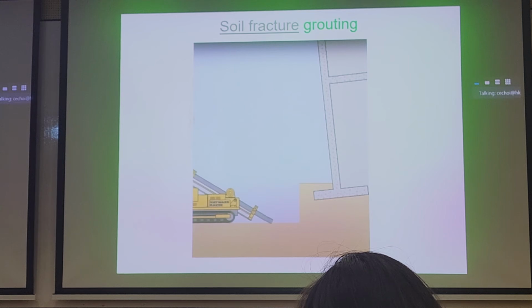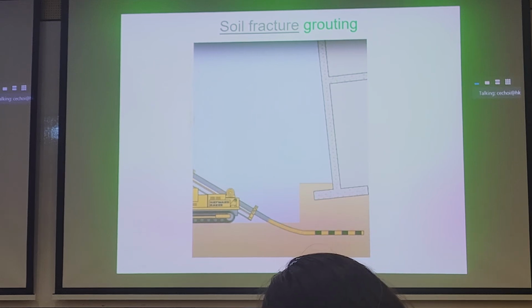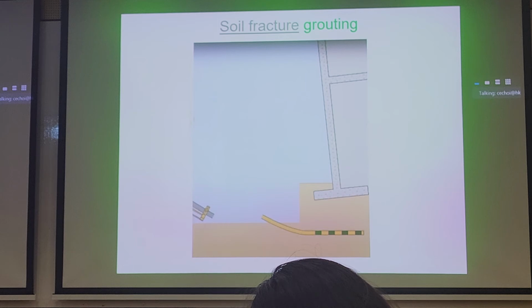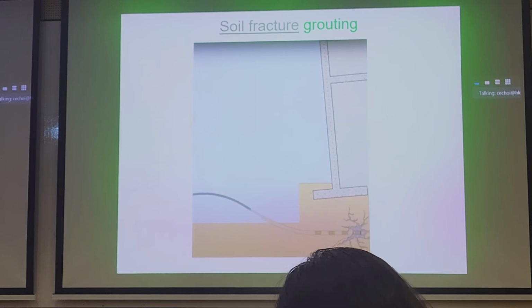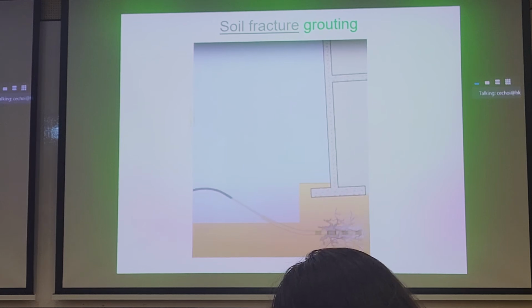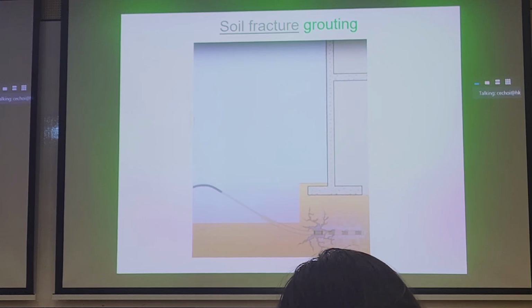So bravely enough, they excavate first. And then they put horizontally drilled TAM pipe again. That's brave to excavate first. Okay, and then now we create these veins in the ground, right? These networks of veins. So it's very high pressure grouting, and we're causing cracks. And these cracks will help to create additional stress in the ground to prop up the soil.